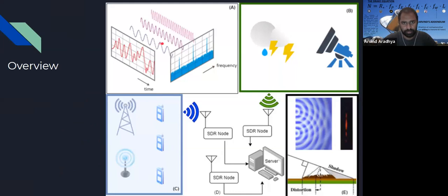This is what I was talking about. Any signal, if you hook up an oscilloscope to your antenna, you see a voltage versus time, which is the signal that's actually induced in your electronics, and that signal can be decomposed into various frequency components. This is done using a Fourier transform, and then you look at the Fourier transform over time, and you can make out that at a certain time you had a peak at a certain frequency, and at another time you didn't have something. Then you basically establish a spectral occupancy footprint, which says that this particular signal needs this entire region of the spectrum to exist, and nothing else should exist in that particular region.